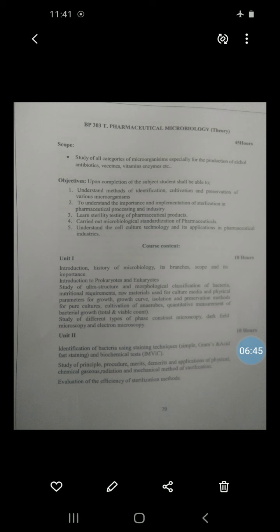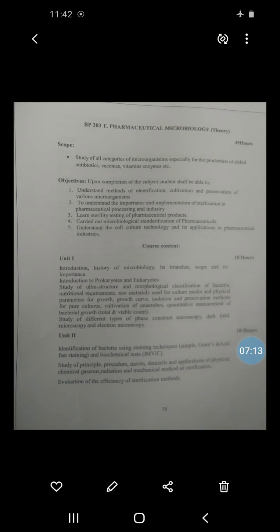The combination of shorter exposure time and improved dose uniformity ratio makes X-ray sterilization a viable processing option for a variety of products. Similar to electron beam, X-ray processing is powered by electricity. Due to the reduced processing time, lead times are improved while maintaining good penetration capability. The adverse effect on products is reduced due to the reduction in exposure time.